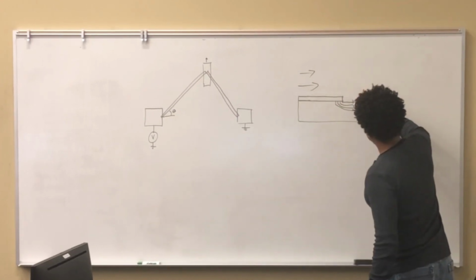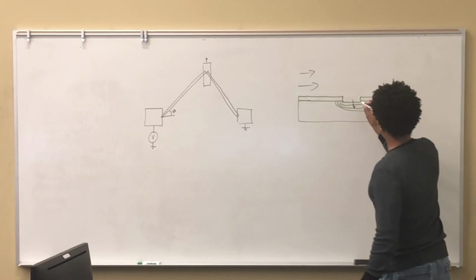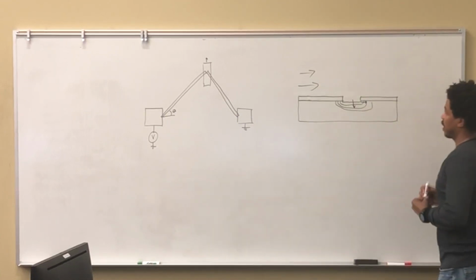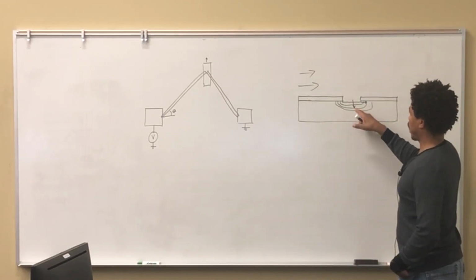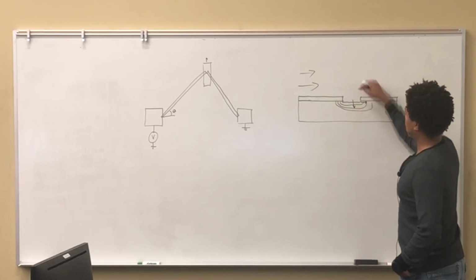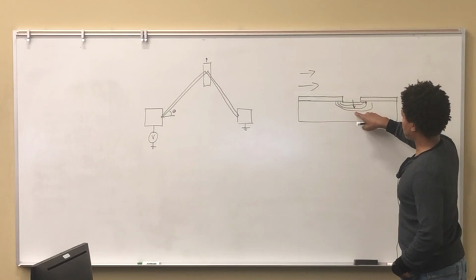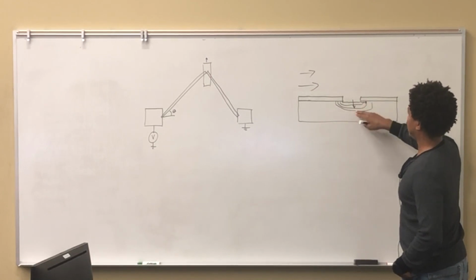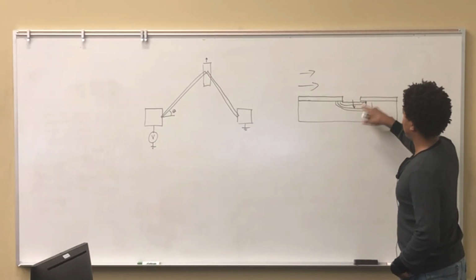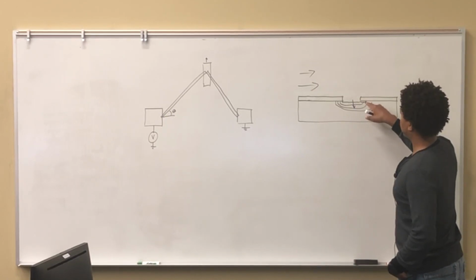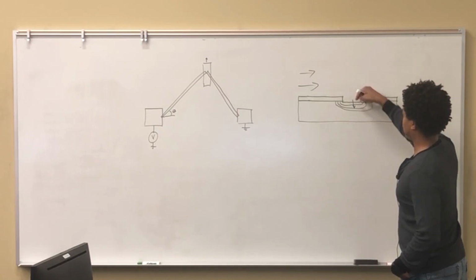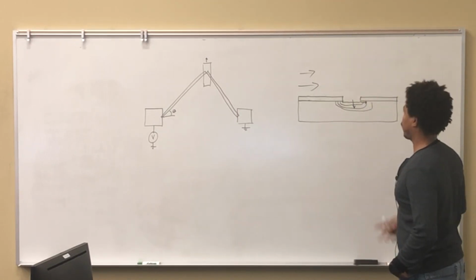Where this direction is etching a whole lot faster than, say, that direction. And the reason is because the mass diffusion rate over here is more open, so some etchant could get through here, attack the surface, and then carry that species out, versus over here where your concentration is a little lower, and so the etch rate on the sides is going a whole lot slower than etch rates going down that direction.